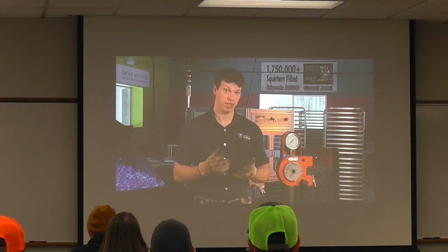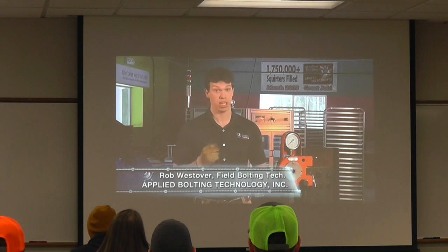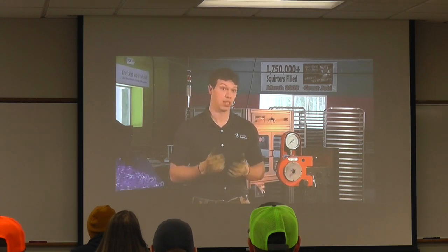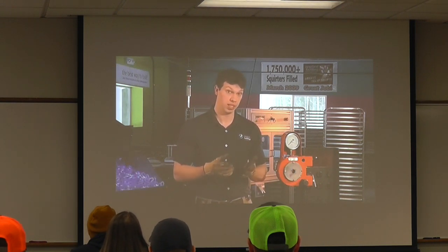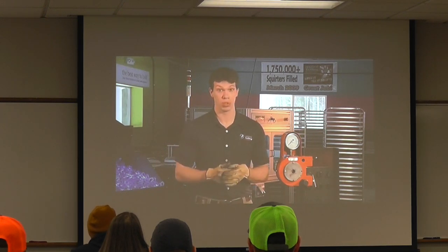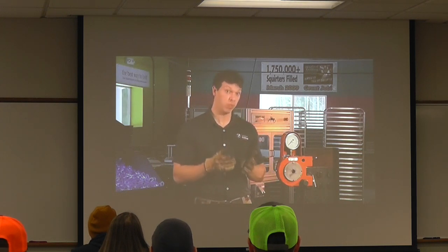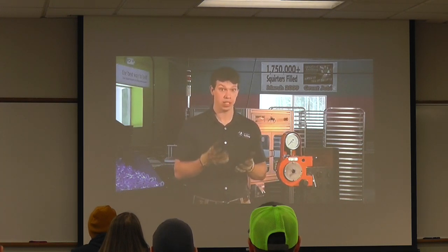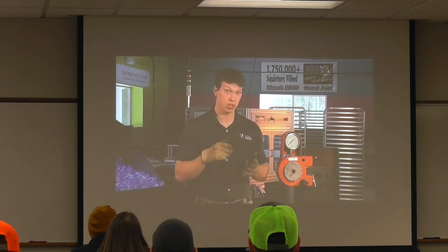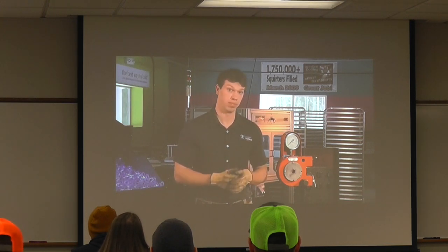The pre-installation verification test is slightly different than the job inspection gap, which we do cover in another clinic. The pre-install test is done to ensure that all bolt assemblies, lubrication, installation methods, and bolt-up crews work together to achieve minimum bolt tension. Now we do this before installation because it is easier and safer to address bolting issues on the ground instead of up in the steel.